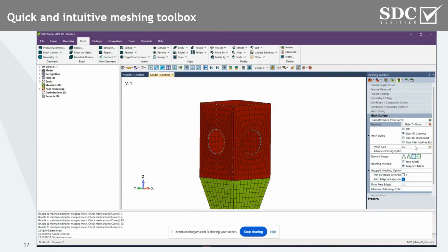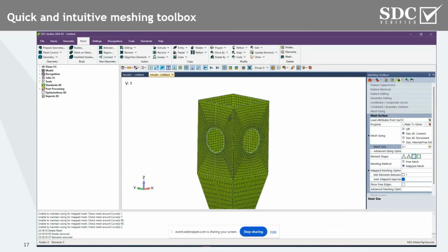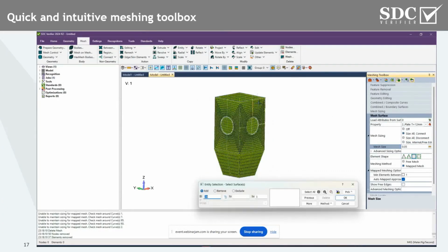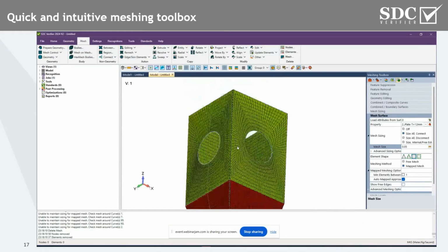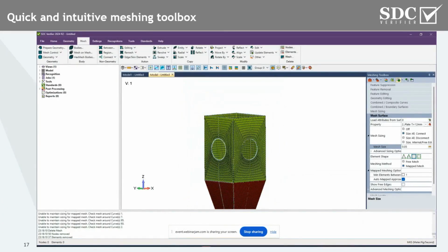So basically, these manholes or these cutouts can be easily handled with a nice mesh quality. And even if you need to quickly increase or refine your mesh, it does it very well, for example, like you can see now on the screen. For different parts, it keeps the mesh flow with a nice element size. But like I mentioned, if you need to locally improve one finite element, two finite elements, specifically in some area because you'd like to get it that way, that's also possible.